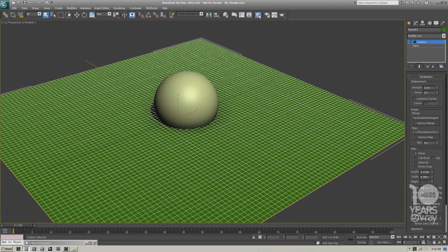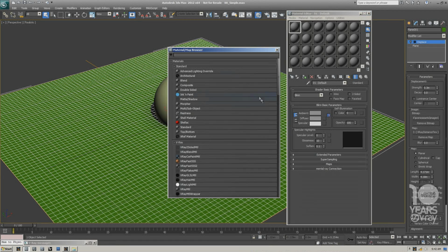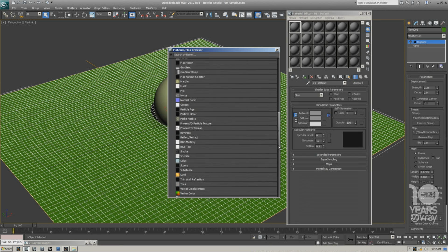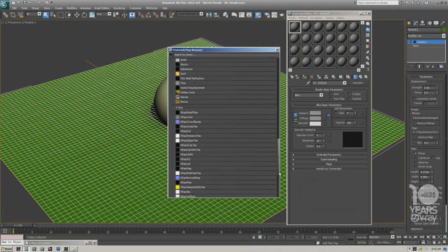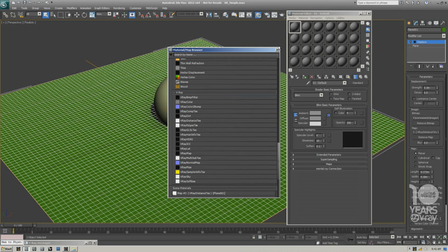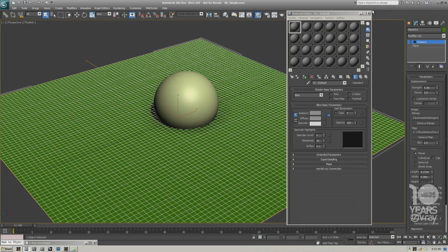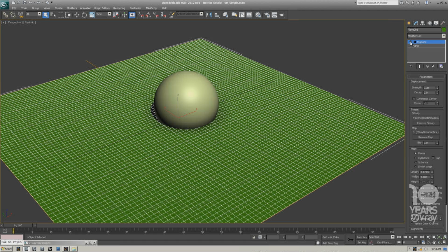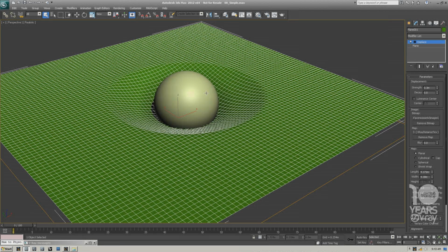The only difference is that the Vray dirt texture was not able to do effects like displacement based on distances between objects because it required actual ray tracing in order to create its effect. That's why we added a new texture, which is called the Vray distance texture. It doesn't require ray tracing, and you can actually displace objects based on the distance between them.